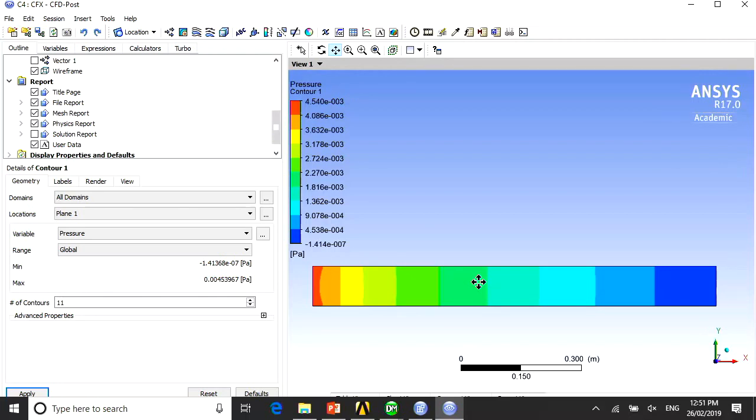Yes. So another thing to note is that you see there's a funny line here, right? It's because you specify uniform velocity, so the flow is still developing. That's why you get a funny line there. By right, it should be straight. If you actually specify a profile here, which corresponds to a parabolic profile, you will not see that line there. It will be totally straight, okay?